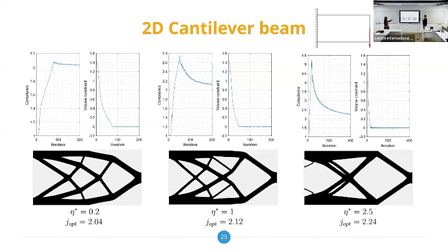So you do not see a correlation between lower eta and higher compliance? Sometimes no. In problems of macrostructures and minimum compliance, generally I would say the lowest eta star gives the better final compliance, because you are going slowly in minimizing the compliance, so it should be better. But I have found other situations where it's not necessarily a relationship.